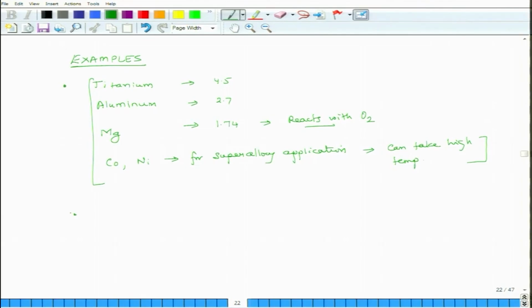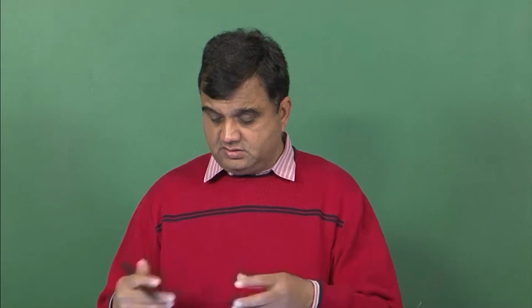Now, these metal matrices are used to bind graphite. So, we do not use these for glass. Glass is a low end fiber. They bind carbon fibers, okay. But then we have to make sure that a lot of these metal matrices, they react with carbon. So, if you bind them with carbon fibers, they react.